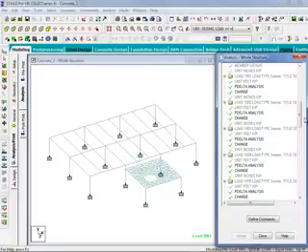Whenever you do have an analysis command, though, after creating a load case and before additional information is added, you should also use your SET NL command. This will be used to specify the maximum number of primary load cases for processing, and it is used in a multiple analysis run when more primary load cases are added after an analysis has been performed.